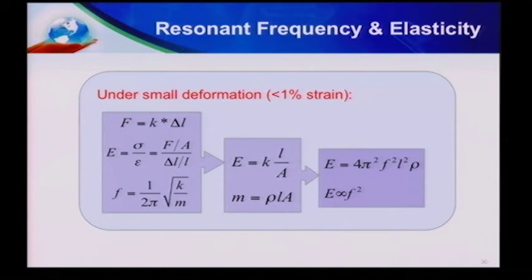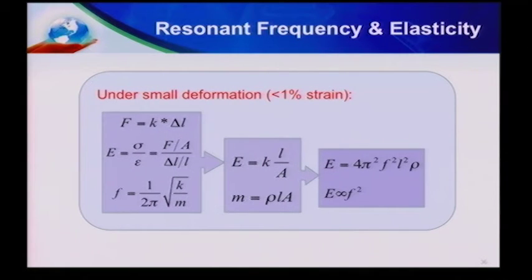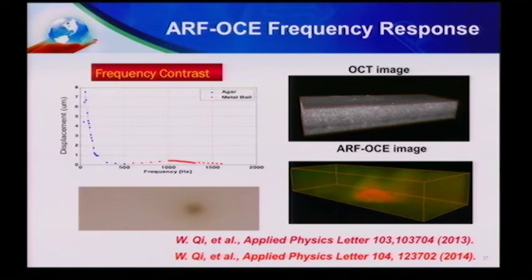If you look at a simple model, assume that the displacement, the force we applied, is small, you can see that there's a really simple relation between the resonant frequency and Young's modulus. So essentially, Young's modulus is proportional to the resonant frequency. In that formula, there is no force term at all. So we can essentially scan the acoustic radiation force